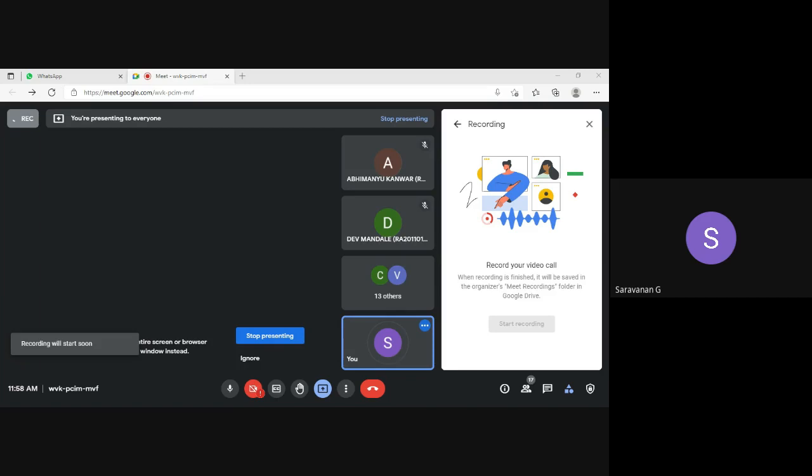Then isochoric, where volume remains constant, a constant volume process. Then S, the isentropic process, where entropy remains constant. Then enthalpy constant, isenthalpic. Then isosteric, where the concentration is constant. And adiabatic, where there is no heat addition or removal, that means no heat transfer. So reversible adiabatic processes are also known as isentropic processes. That is all we have discussed in the previous sessions. We will come to the discussion of each and every process and the equations or relations corresponding to those processes in the next sessions.